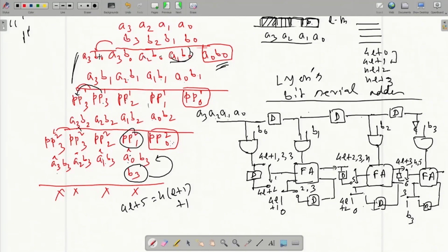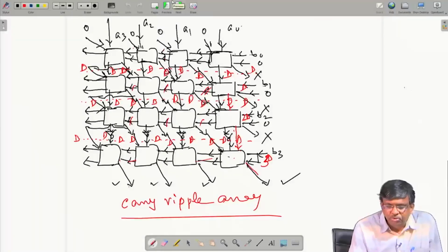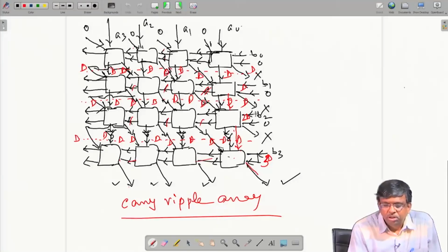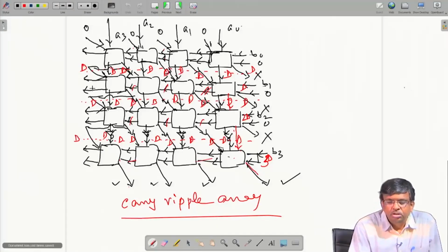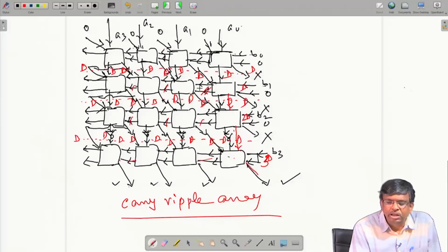Similarly, if you go further beyond, see this array. Okay, what does the array do? If you have got some of the bits 0, the entire operation here is not required. So, this row can be skipped. For instance, suppose B0 is 0 or say B1 is 0. So, B1 dot A0 which is 0 plus incoming, so incoming remains as it is. And no carry gets generated, and same here. So, this easily goes away.